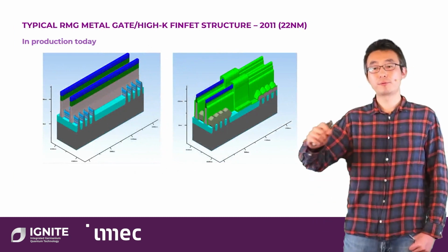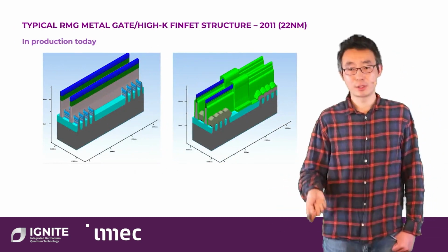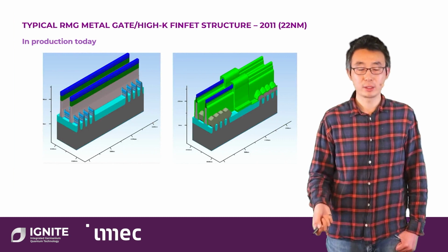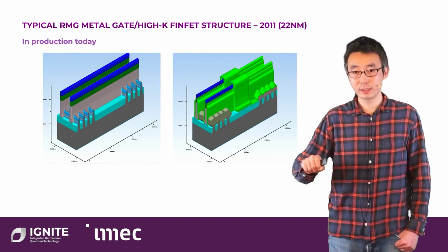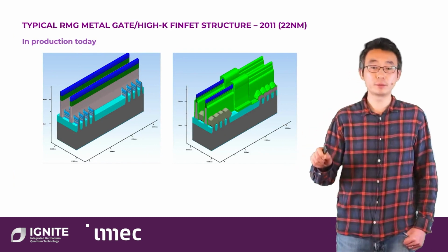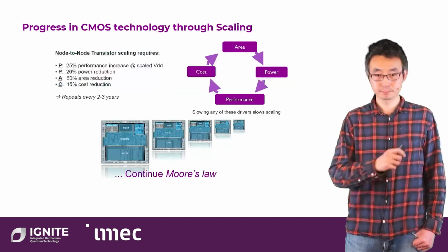And towards even further scaling, you need better control of the channel. That's why you need to introduce the FinFET. Essentially, the current flows inside the fins and you have the gate wrapped around the fin to control the current.